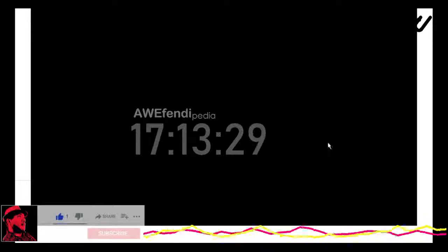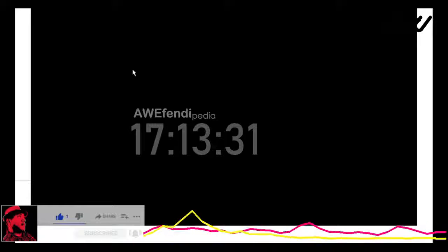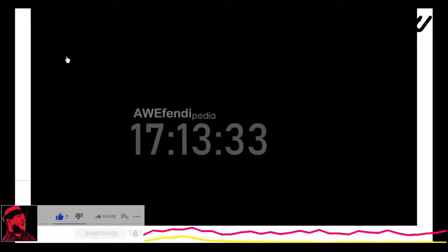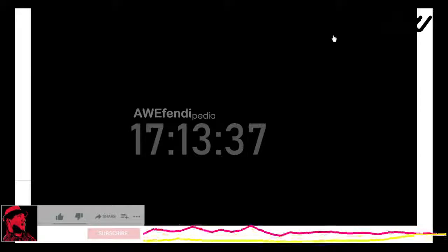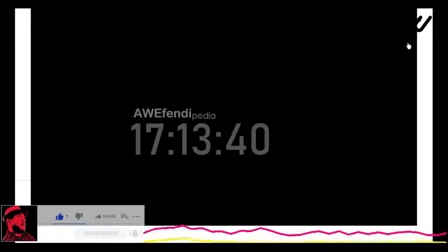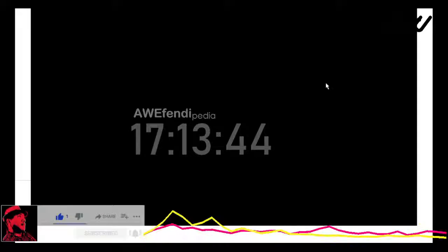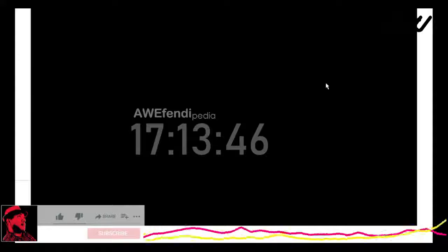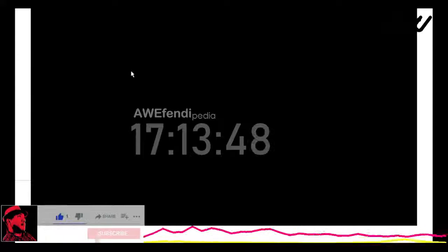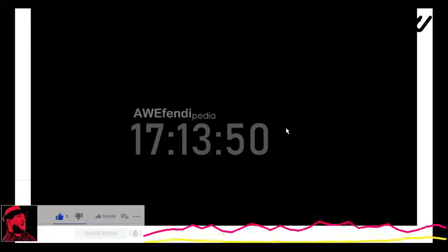We're going to add 12 feet and shoulders to the inside of this divided, bifurcated roadway. In doing that, you'll notice we want to modify the PGL between these roadways. As we widen to the middle, if you'll notice, the existing roadway is quite a bit higher here, we want to be sure to maintain a more level elevation between the two roadways from left to right.